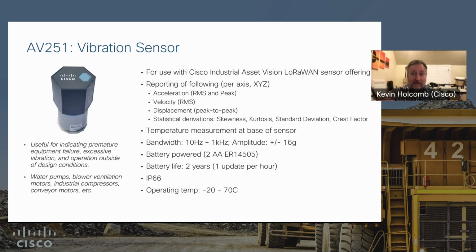So now when it gets to you in the cloud, you can start to look at what's normal for this sensor. Maybe the velocity RMS is normally at a certain level, and all of a sudden it gets higher than that, right? You can do it that way and get an alert. Another way to look at it is, there are ISO specs out there that specify if you have this horsepower of machine mounted in this way, the velocity RMS should not be higher than this, right? There are different zones. There's the green zone, everything's okay. There's a yellow zone where it's like, okay, you can still run this machine, but go check on it when you get a chance. And then there's a red zone where it's like, don't even operate this machine anymore, right? So that would be an even simpler way of doing monitoring.